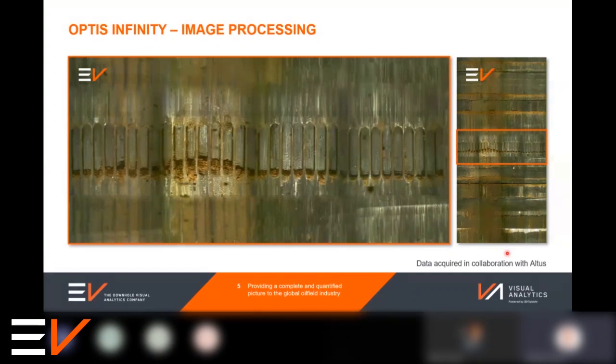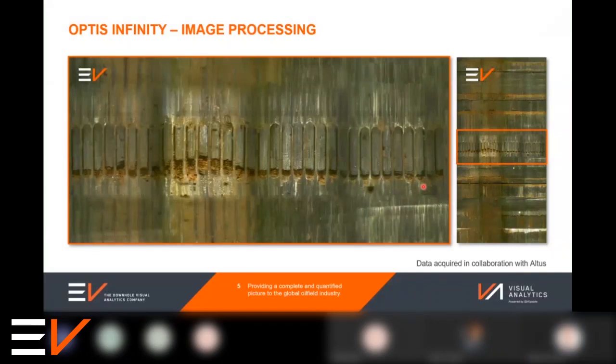And you can see the level of detail that we can capture with this video system. Not only the individual ports, but some of the marks on the inside pipe wall, and even the presence of some very light, soft solids that have accumulated on the low side of this assembly. These were identified as small bits of bacterial growth that were floating freely in some parts, but also had become settled at the low side of these ports there.